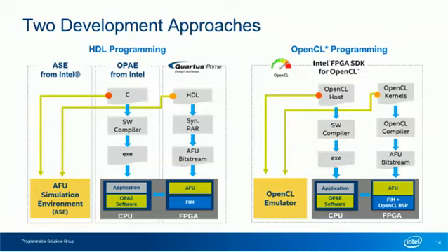The SDK, with the help of a traditional software compiler, will also generate the appropriate software code that is run on the CPU. Users will need to know the OpenCL host API and not the OPAE interface. Before creating the actual bitstream, the OpenCL flow allows users to emulate the OpenCL C kernel on x86 machines to easily perform functional debug. This flow is more productive of the two.